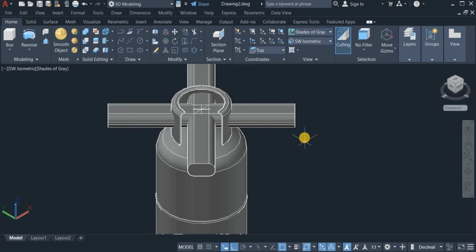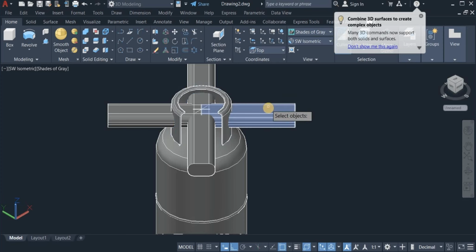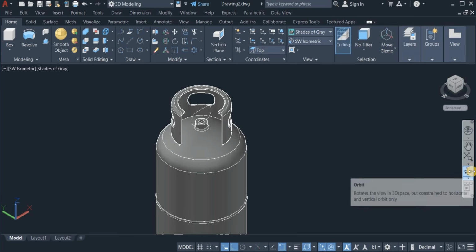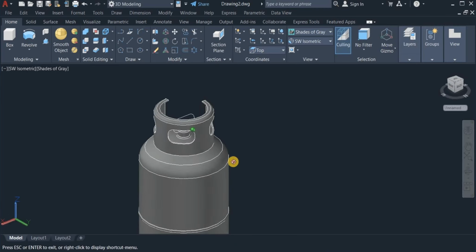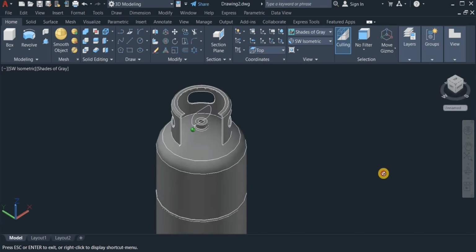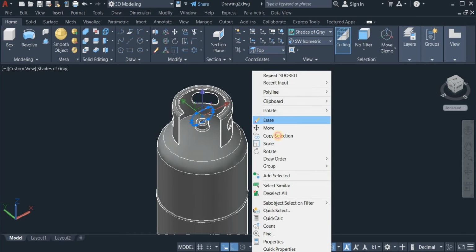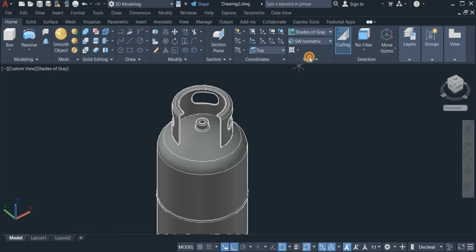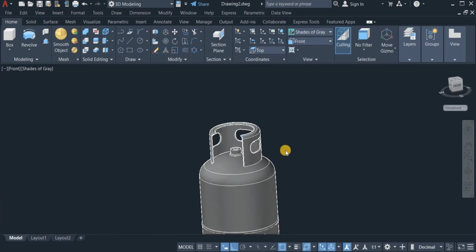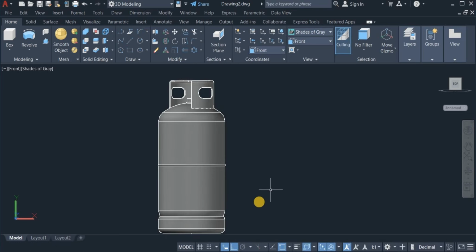Okay. So I've now used the solid subtract command to subtract these ones from this. So come over to the solid editing panel, click on solid subtract, click on this first, then subtract this, this, this, and this. Alright, so this is what I have now. Let's see how that looks like. Okay. So delete this very one now. Okay, now switch again back to front view.